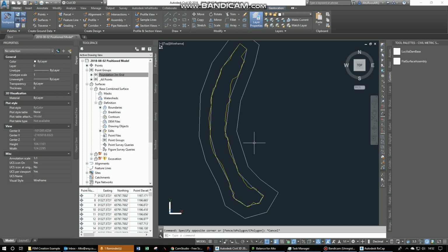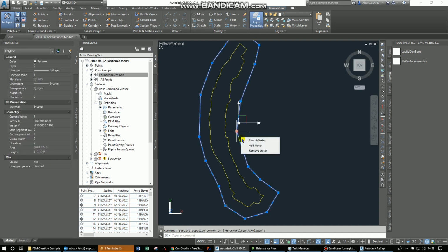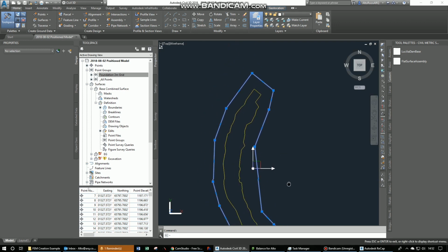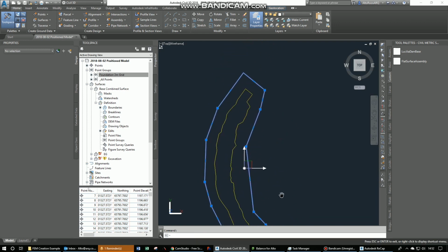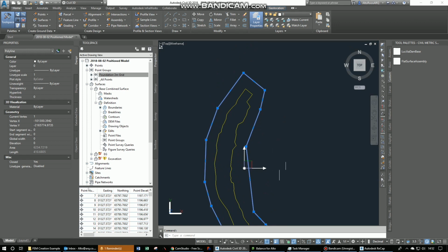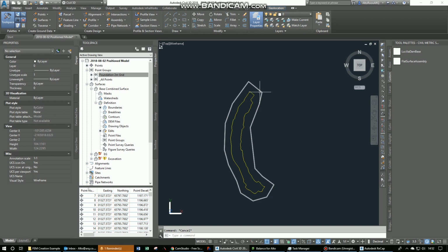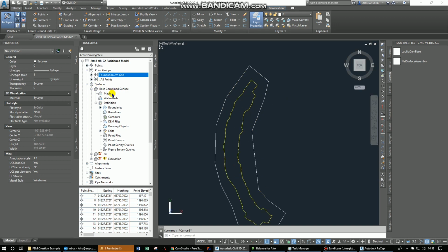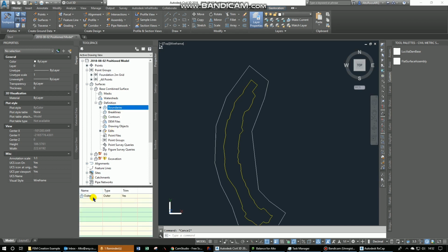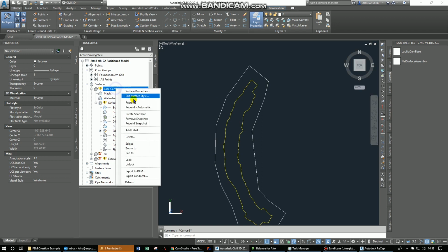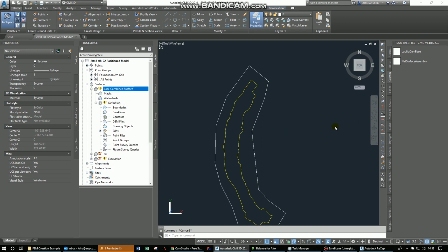That looks okay, but let's remove this line now. We don't need that anymore. And let's keep it a little bit more refined over there. That should be relatively okay. You can obviously add as many points on this boundary as you'd like, and perhaps you've got a specific zone on one of the banks that you would like to be well refined as well. Anyway, in this case we don't. For now, let's remove the boundary that we added initially. So now it'll pop back if we rebuild the surface to the outer one that we had initially.